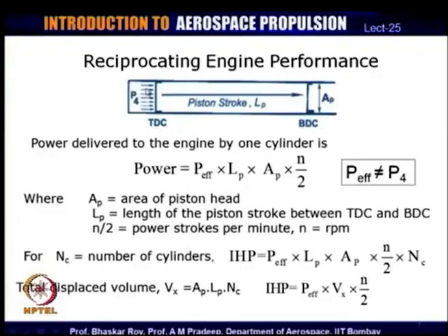As a result it exerts a lot of force on the head of the piston, often called the piston head, and this has an area. Obviously, the more the area of the piston head, the more the force is likely to be, but as we have seen the aircraft engine has certain limitations of its size and weight, and as a result the size and weight are often a little restricted. So, the pressure here creates the force which then starts driving the piston through its power stroke. That means, its motion backwards from TDC to BDC, and it executes the power stroke.